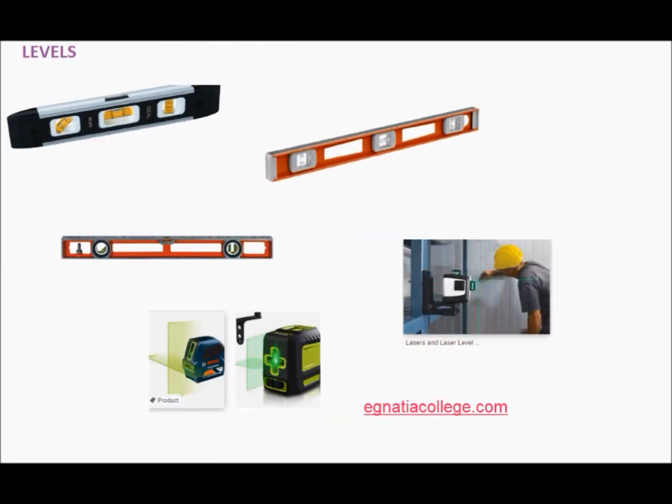Levels. A level has tubes known as vials that are partially filled with colored liquid, leaving a trapped air bubble inside to read desired results. Drainage pipes are installed with slopes so that wastewater flows out of the piping system, but other piping systems and fixtures are installed with levels. Most quality levels have 3 different leveling tubes for 3 different installation positions. One tube is for vertical readings, one is for horizontal readings, and the third is for 45 degrees readings.